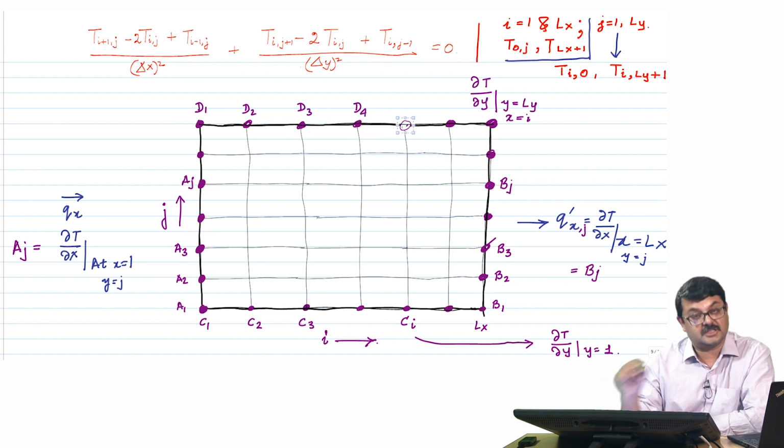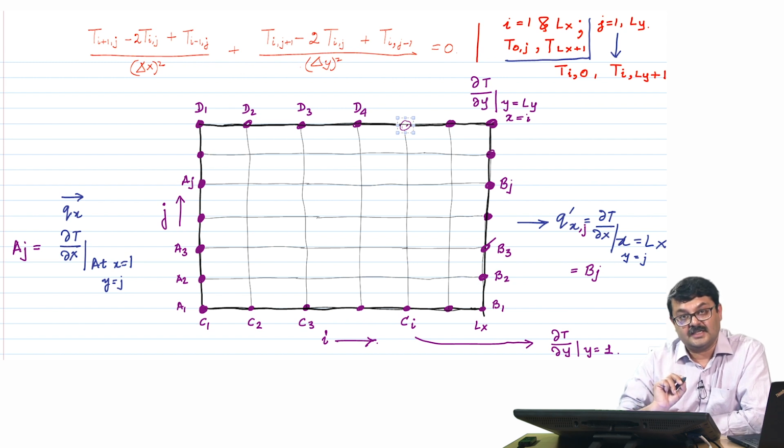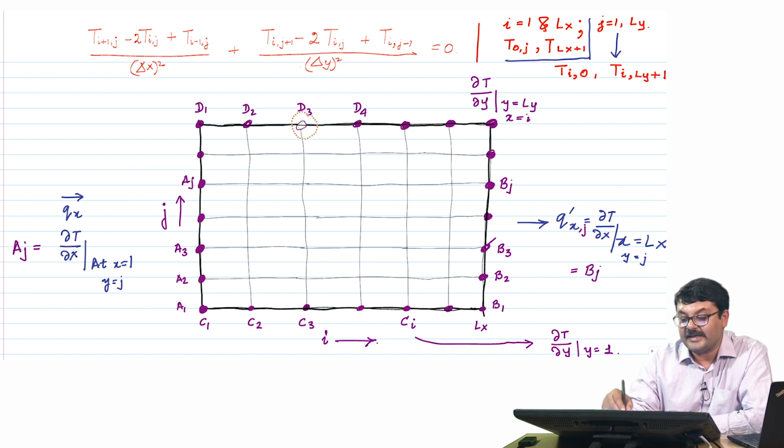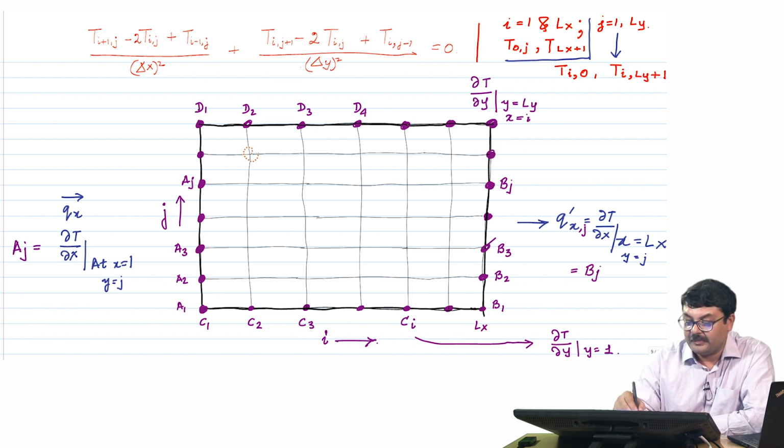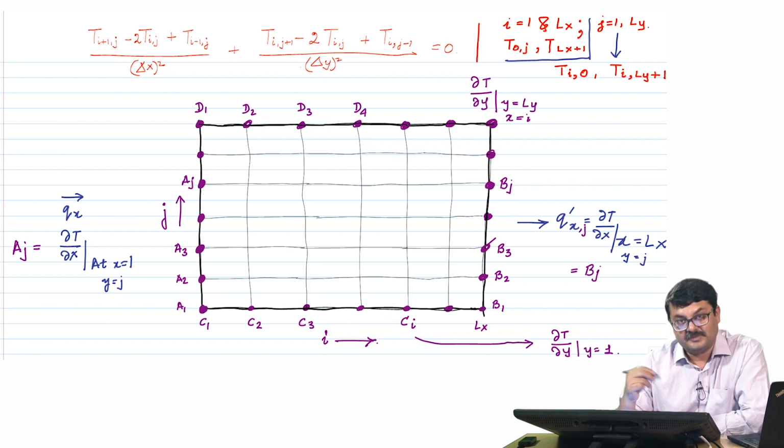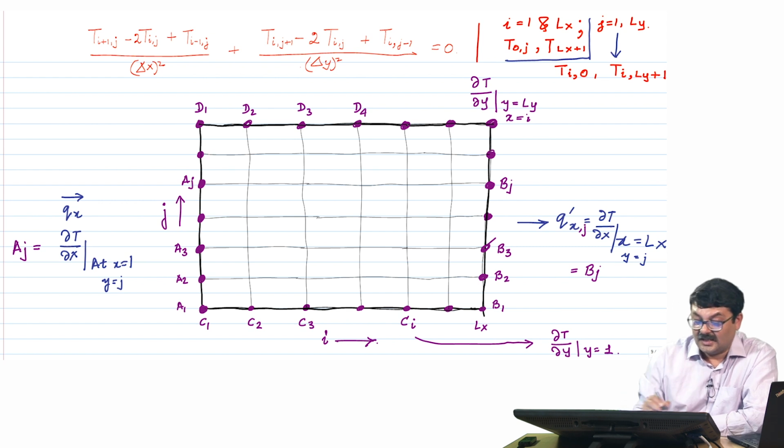So, they were fixed at the boundaries. As a consequence, we were not changing or updating the value of the temperature at these boundaries, because they were considered to remain fixed, and we were only updating and finding out the steady state temperature of the points within the lattice. We were basically solving for those iteratively.